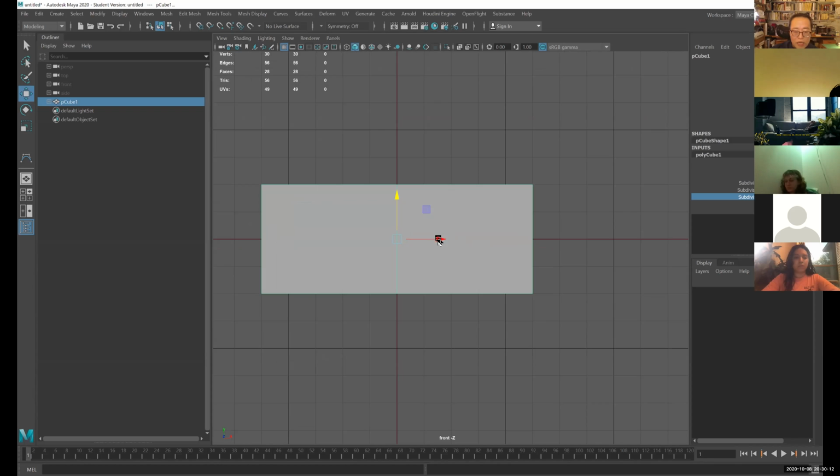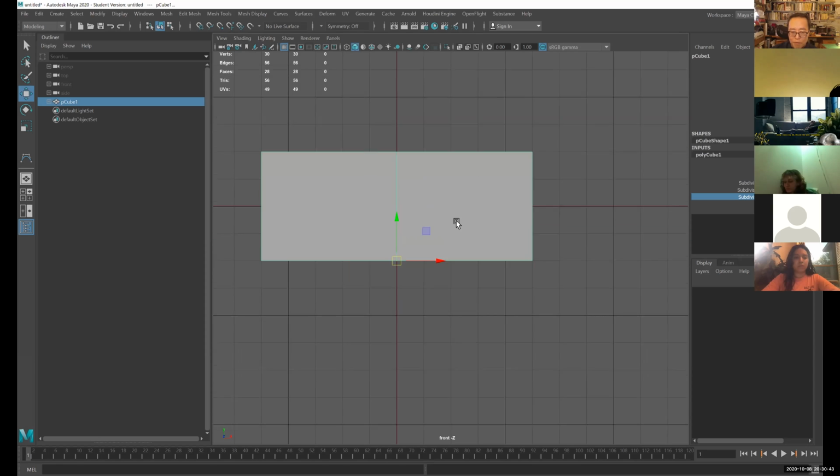So in order to reset the pivot point here, you press the D key, and then you can click and drag the pivot point to another place. And in order to snap this to the bottom here, there are vertices available on this object, so it will be combining the D key with the V key. DV is the combination of keys. You see how that moves the pivot point with the D, but also with the V key it snaps the pivot point to the bottom.